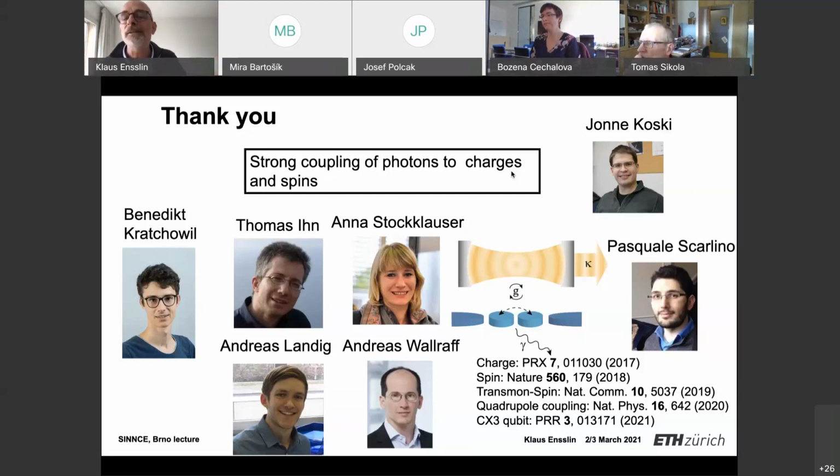And lower frequencies are difficult because once your frequency is less than kT, and let's say we take 100 millikelvin, you need a gigahertz so that the energy is larger than kT. So there's a lower cutoff that makes sense, and then there's a higher cutoff which is more or less given by technology. Everything above 10 gigahertz is possible, but requires a very different approach. All the plugs in your cryostat and so on wouldn't work anymore.